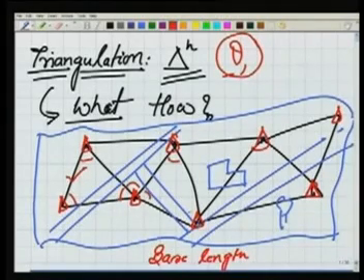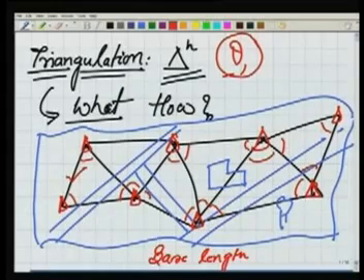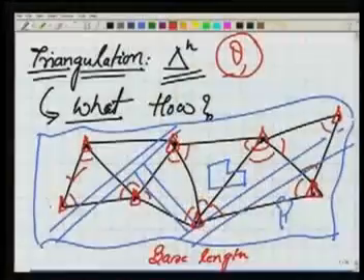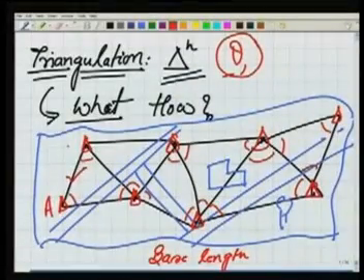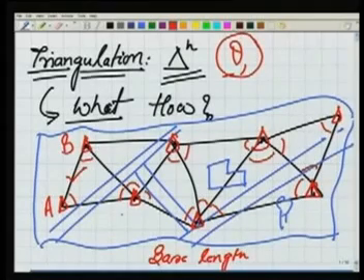So all these internal angles of the triangulation figure are measured. What we did, we measured the length only once for only one line, but we are measuring all other angles. Now you know that it is very easy to measure the angles, because you have to be physically in one place. You have to just bisect the targets. So standing at this point A, you can bisect a target at B and a target at C, and the angle is measured. But to measure the length, if the EDMI is not available, what do you have to do?